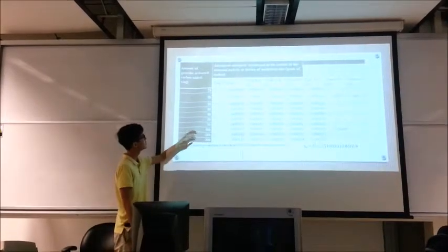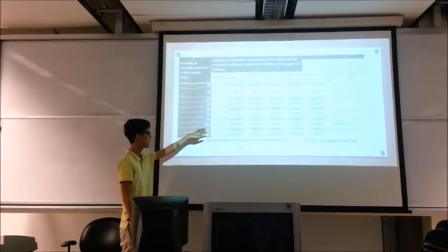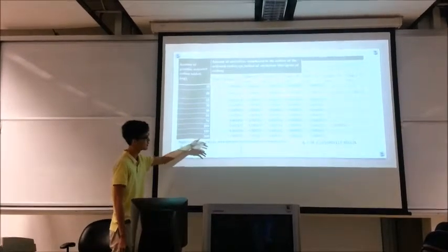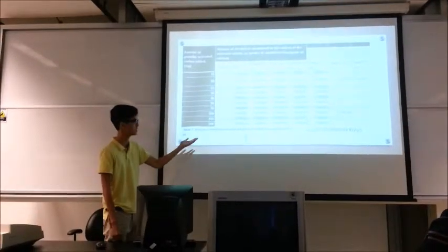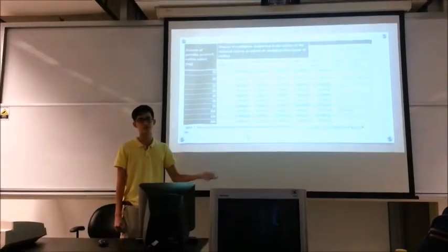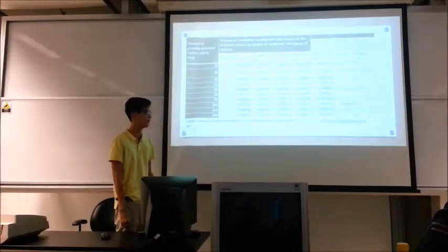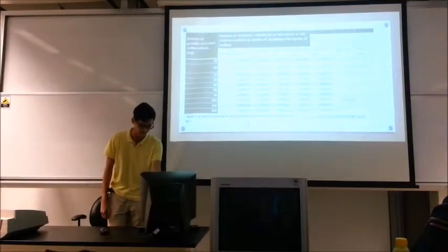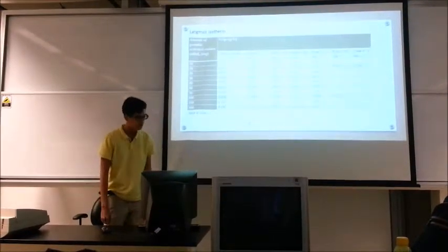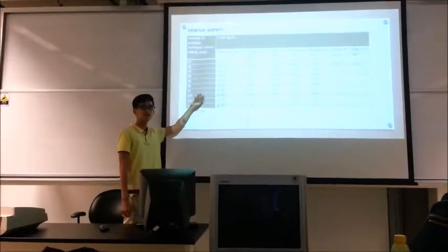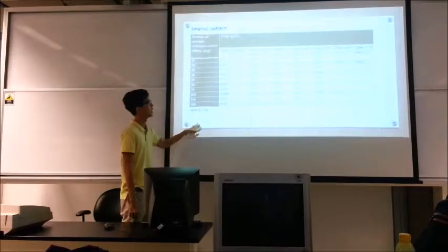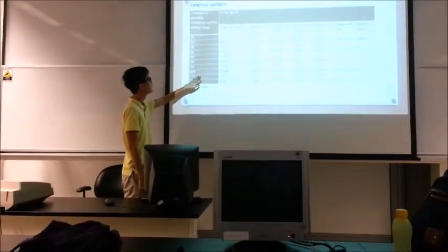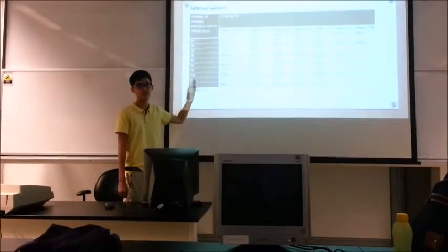And this table is about QE, which is also calculated using the same formula as shown before, which is C minus C naught divided by 1000 times 319.85 divided by the amount of granular activated carbon added. As for the Langmuir isotherm, we have to calculate C divided by QE, and this table shows what we have calculated.